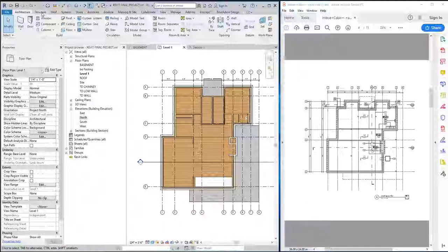The way that Kevin likes to do them is he likes to use the assembled stairs. So he likes to take components, like a component stair. He likes to add a landing, a stair run, a landing, a stair run, and use predefined pieces in Revit to create his stairs, right? Which is completely valid. I have a harder time getting those to work for me. And when I'm adding stairs, in this case, it's fairly straightforward.